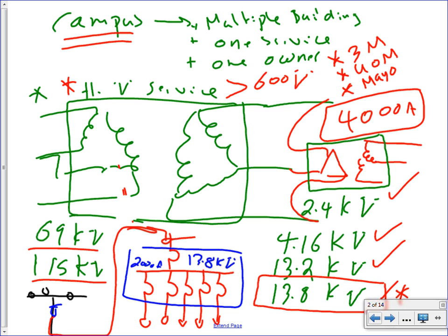You install this cable up to the red point. Now Excel comes here and they tie this side into their power system, and this is three-phase. That makes sense? Right at the pole. Then you install that with MV90 or whatever it would be, the one that's coming right underground. Now, if you're going overhead, they use aluminum conductor steel reinforced, ACSR.